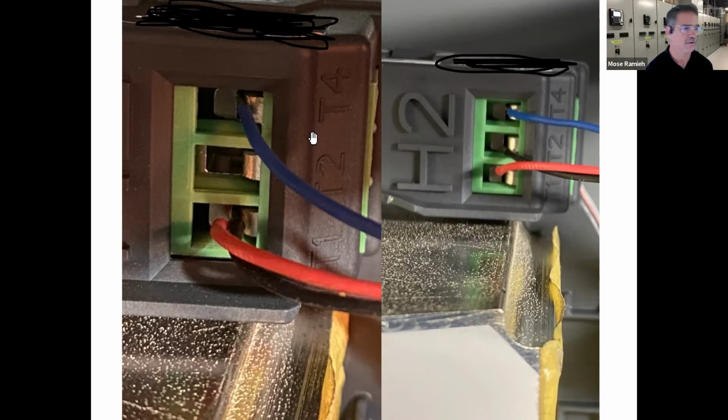It was tripping both when we injected it and expected it to trip, and when we injected it and didn't expect it to trip. Some investigation found that, you'll notice right here, we've got a red and black wire, both landed in slot T1, nothing in T2. A quick review of the drawings, and we could see that the black wire is supposed to be in T2, red wire in T1. Made that change, retested it. Now the system's working properly again.